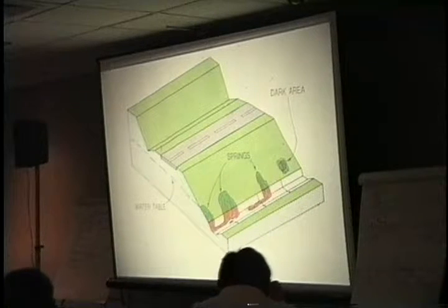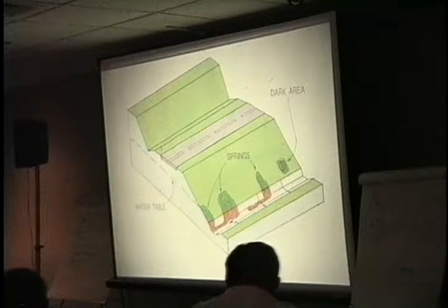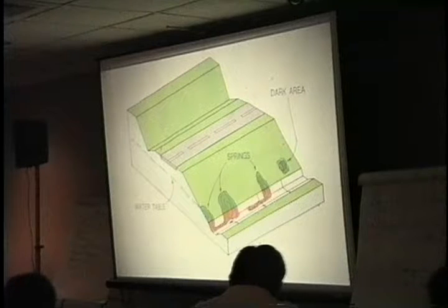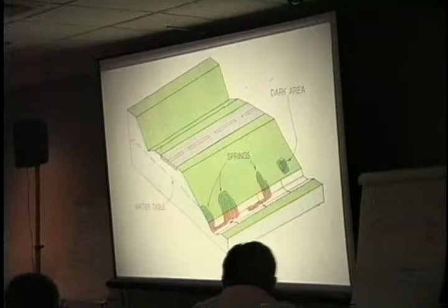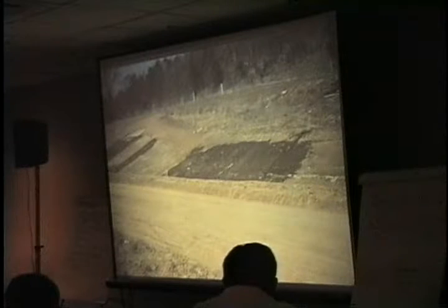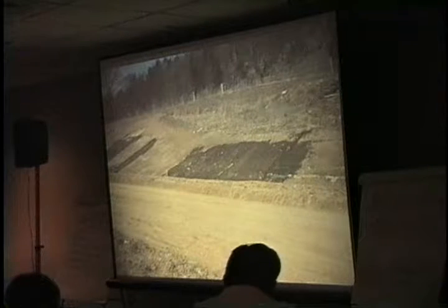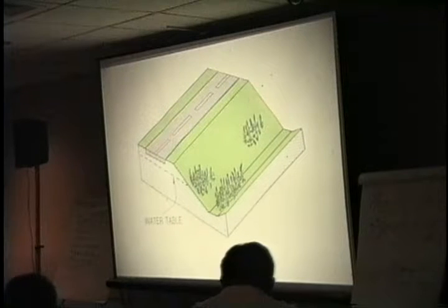If you've got poor drainage because of gravity in those side ditches, we might have to put in a French drain and drain it by gravity. Little water on the side slopes. Cattails.